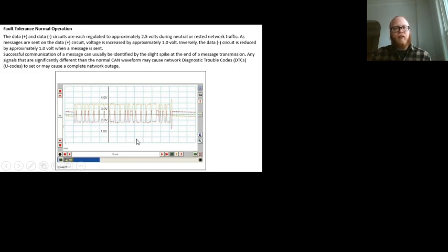My x-axis is time, and it's very hard to see, but that says 20 microseconds. There's a weird little m called a mu in there. Each one of these divisions is 20 microseconds, is 0.00002 seconds. So this is happening incredibly quickly, right? I said this is our high speed.